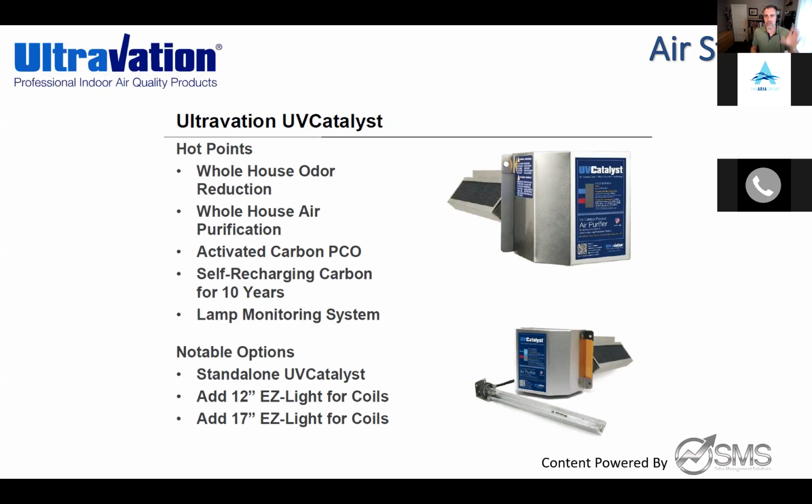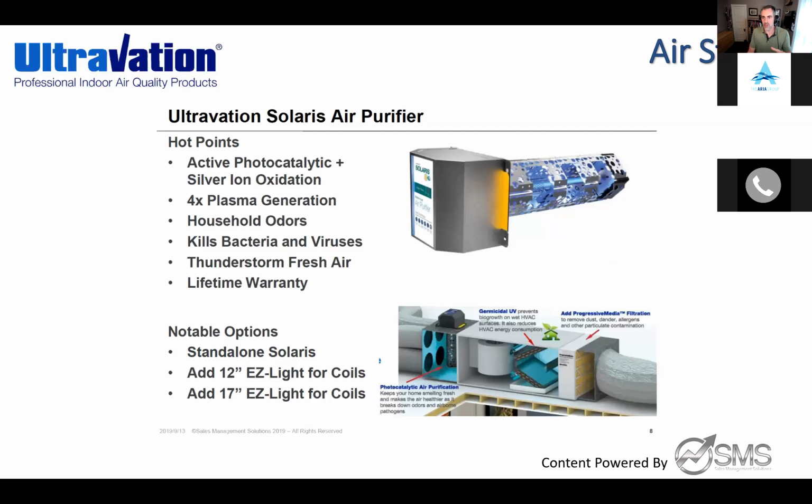People say, oh, I just want to turn them off with the system. I'm like, no. The other problem is UVC bulbs are not designed to do that. This isn't like a light bulb. A light bulb's filament can be turned on and off like that. A traditional one, in the UV world, no. You just power it up and leave it going 24/7. They use less energy than a light bulb. They're just there to inhibit growth and create that reaction.